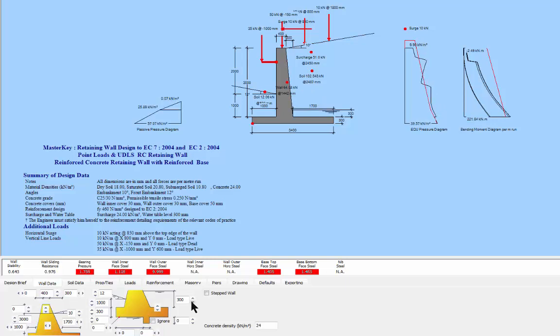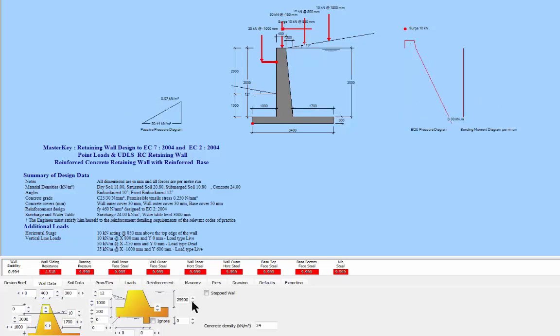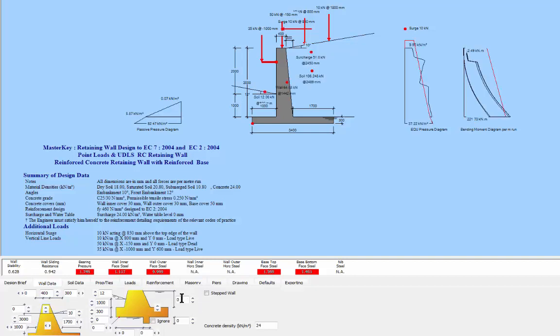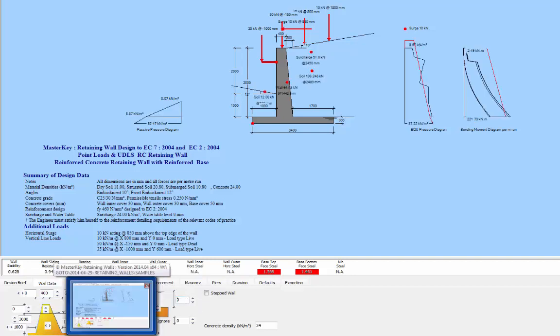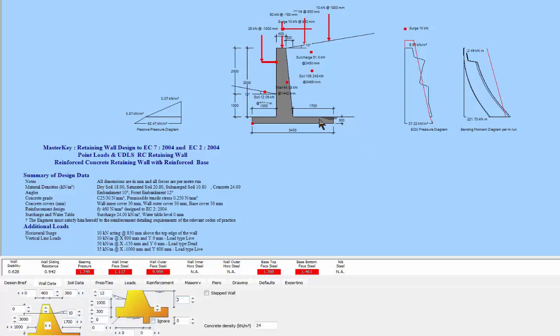Down comes your hydrostatic loading, and what you actually do is you put in a negative. So at the minute it's the top of the base space, so I'm going to say minus 500, and that just says, get out of my way. I don't have any hydrostatic. So that's removing the hydrostatic pressure. So I'm going to put that back on again just so that this is complete.